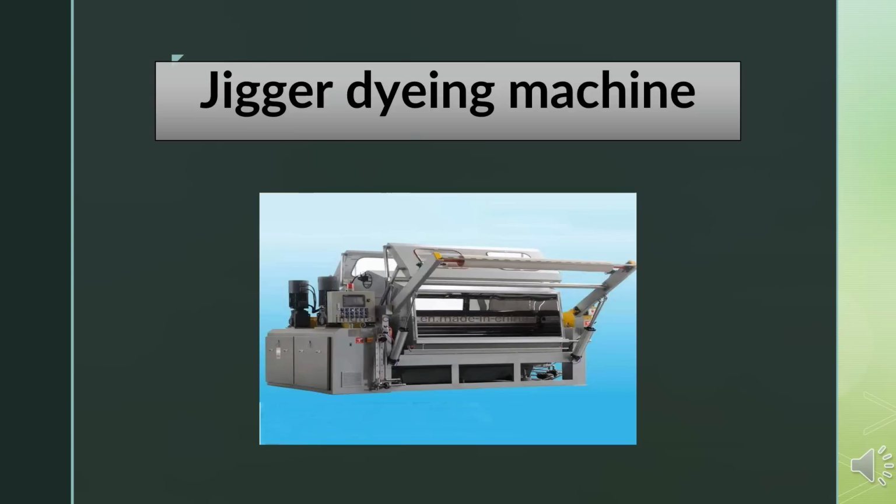Once a full passage is completed, it is passed reversibly from the second roll to the first, ensuring that it passes through the bath of color as it did in the first case. The number of such passages depends on the depth of shade that is to be achieved. Here, there are two visible disadvantages.